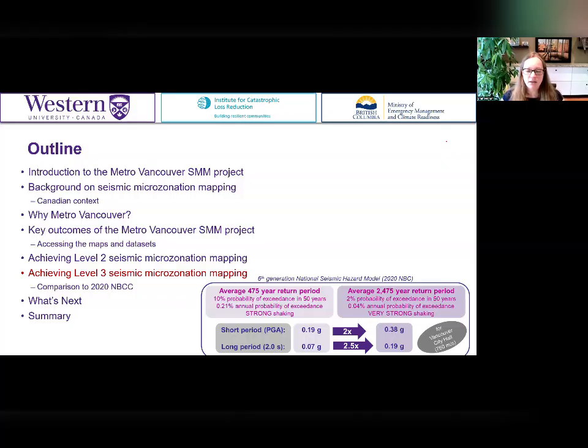The other key piece to say is that the shorter return period, more frequent type earthquakes, that lower shaking intensity is more probable to occur more frequently. That level gets increased by 2 to 2.5 times by the second level of shaking intensity that we look at. The differences in the maps for the two different return periods is that the shaking intensity that we considered has been increased by about a factor of 2 to 2.5.